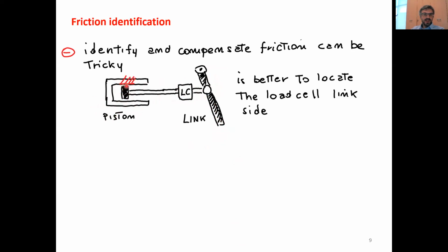And rather than measuring, for example, the load torque by measuring the difference in pressure of the chambers, which tells you the hydraulic force, you can measure the force that the piston applies using the pressure difference of the chambers multiplied by the difference of area.